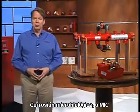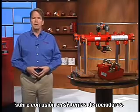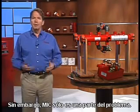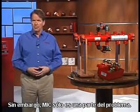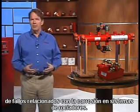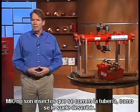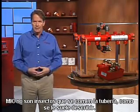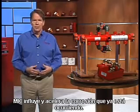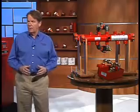Microbiologically influenced corrosion, or MIC, has long been the buzzword for corrosion in fire sprinkler systems. However, MIC is only part of the problem. MIC is not the root cause of corrosion-related failure in fire sprinkler systems. MIC is not pipe-eating bugs, as often described. MIC is an influencer and accelerator of corrosion that is already occurring.